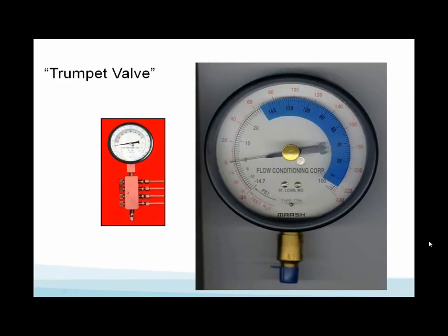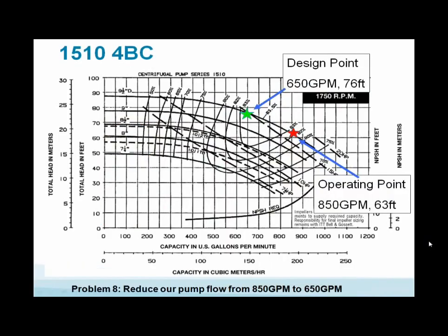I like a pressure gauge that gives me differential pressure. Here's our gauge that's made for water, specific gravity of 1, that shows feet of head. And it's got multiple tappings to it, you can see. So I have one tapping to the suction flange, one tapping to the discharge flange of my pump, and I get differential pressure in feet of head.